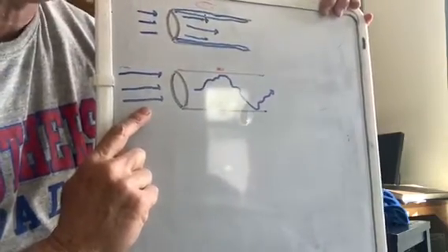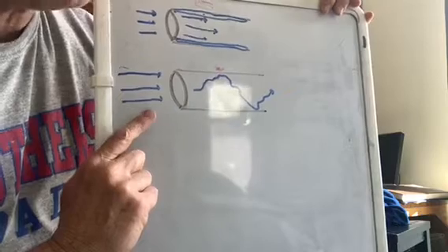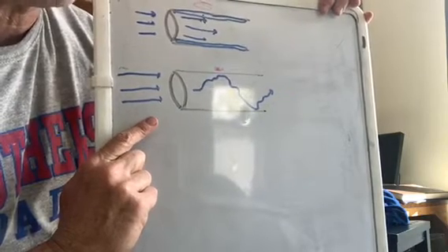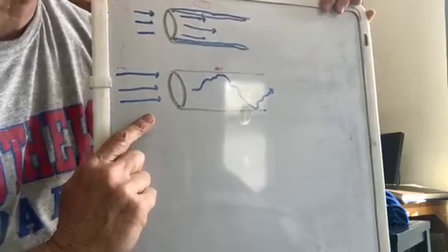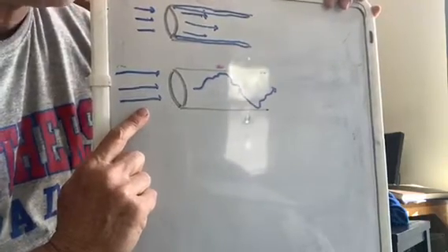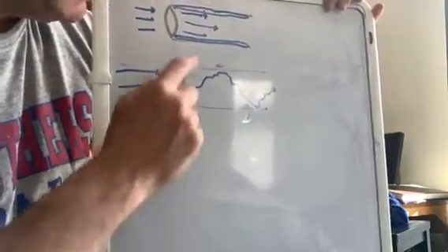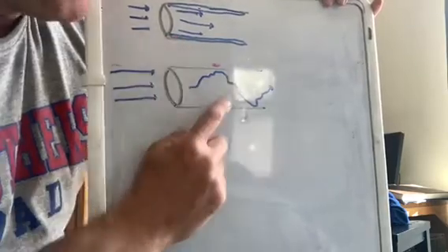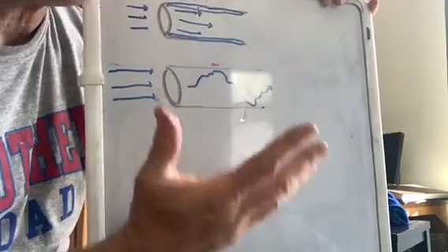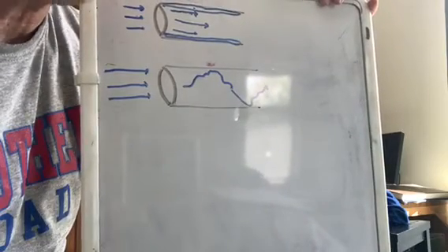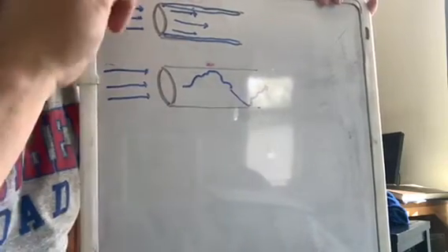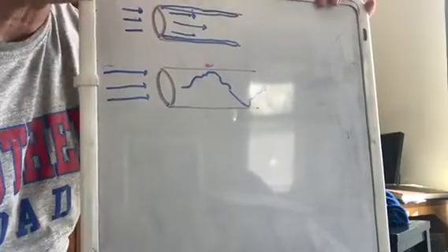Well, increasing the flow rate involves more pumping energy. So it's something that's very, very important for us to just hit right. And it turns out that it is worth increasing the pump speed enough to get beyond laminar just into turbulent, and then after that there's not much benefit. So we want to be able to pinpoint what flow rate is right, and let's work on that and remind you guys how to do that.